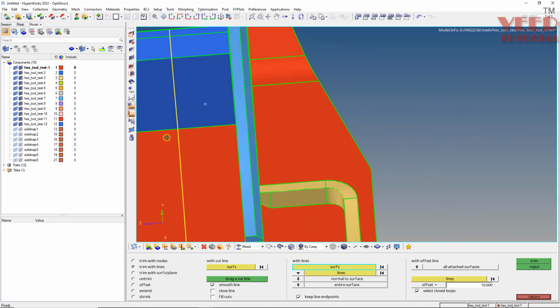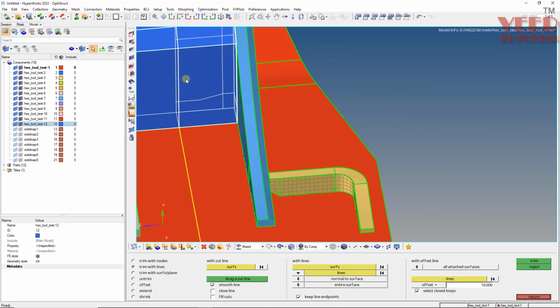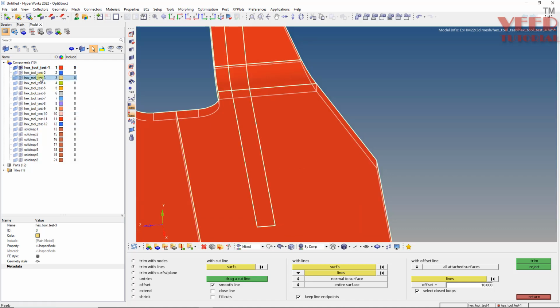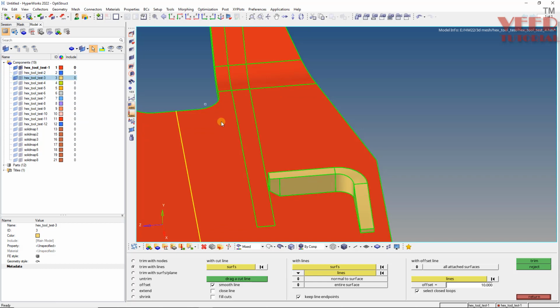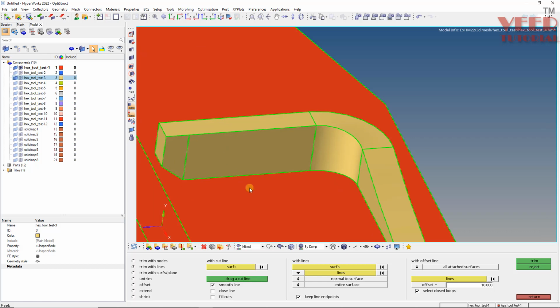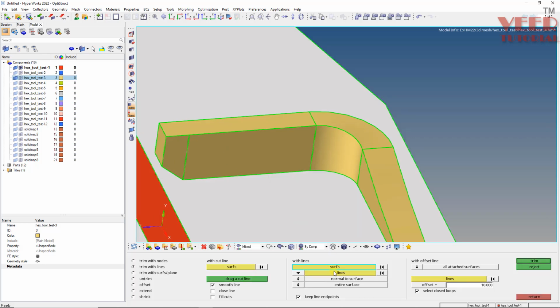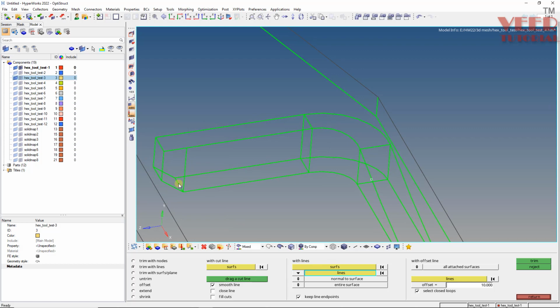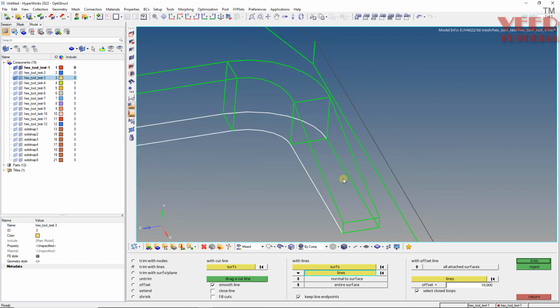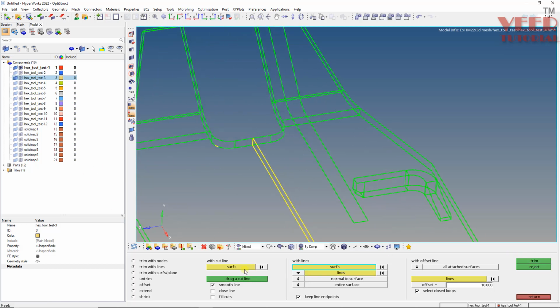Okay, so this blue part is part number 12 and this is part number 3. Okay, right click, isolate only, turn on part number this, and now I will go to once again surface edit, select this and all this, delete and trim, and after that part number 12,